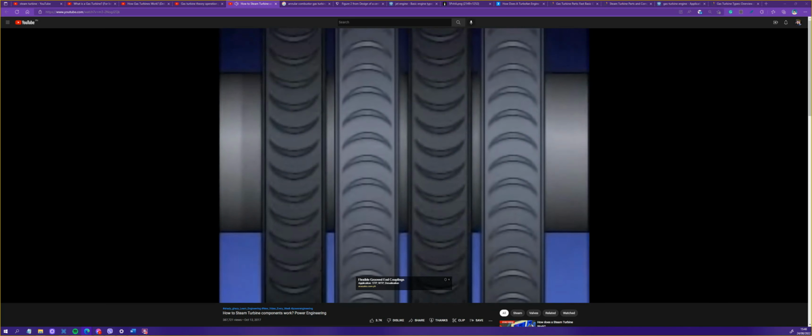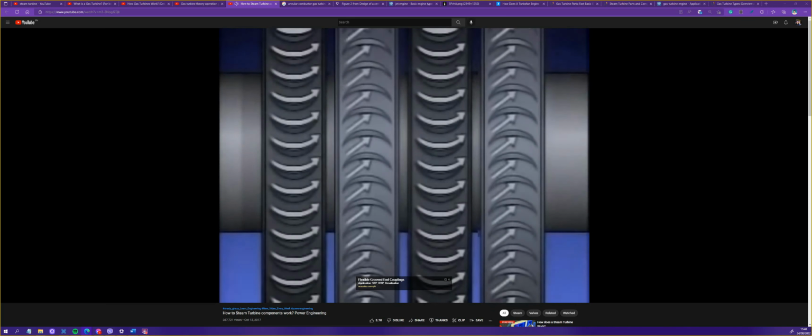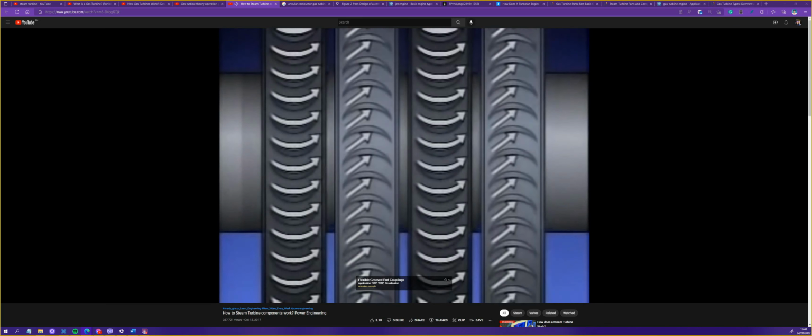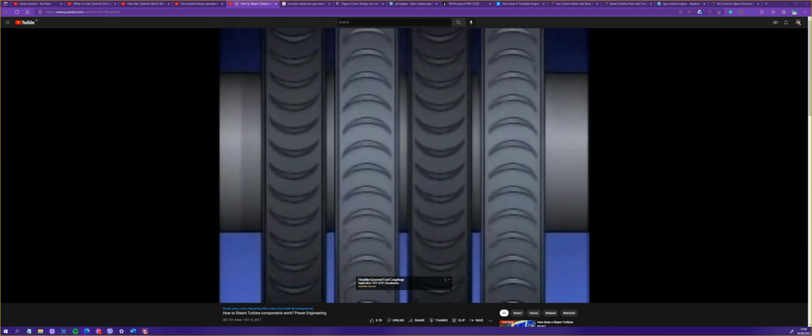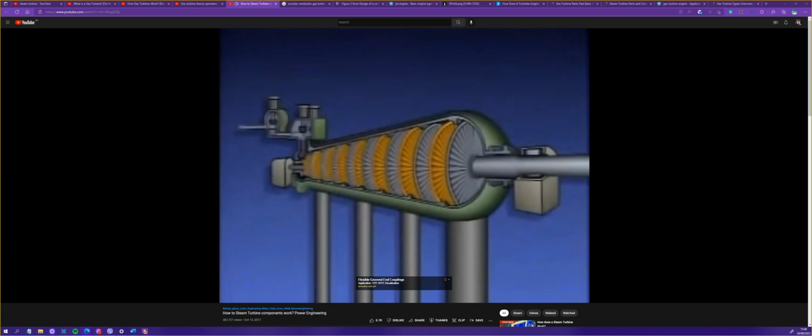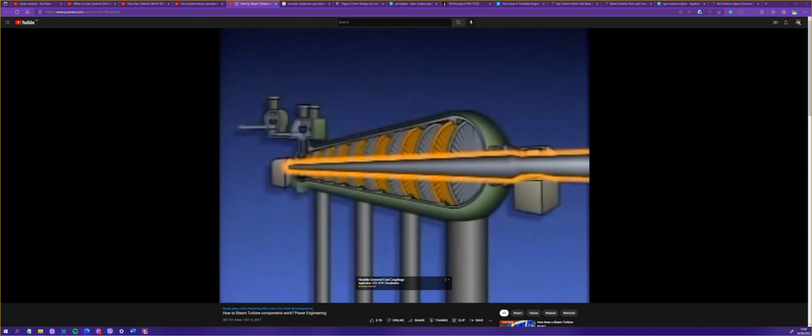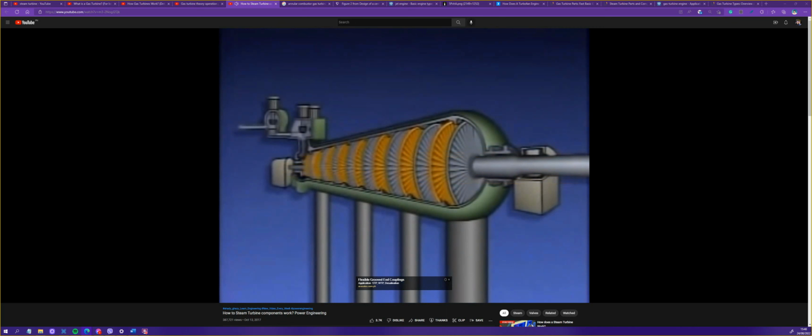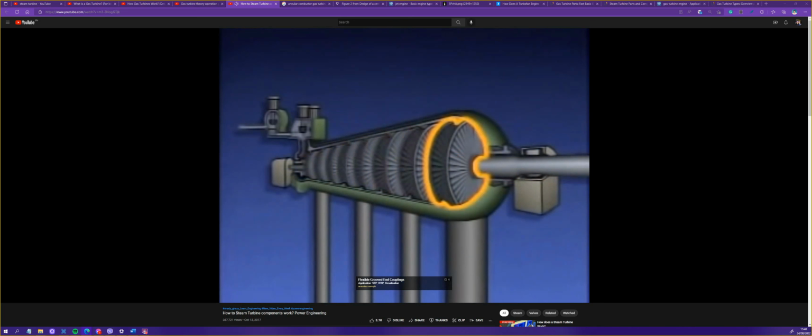They are designed to turn as the steam flow passes through their rotating blades. The rotation of the wheels turns the shaft and the generator. Diaphragms are sealed where the shaft passes through them to minimize steam leaking through this opening and bypassing the diaphragms. Typically, the pairing of one diaphragm and one wheel is called a stage.